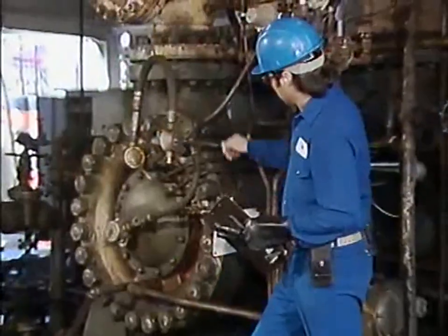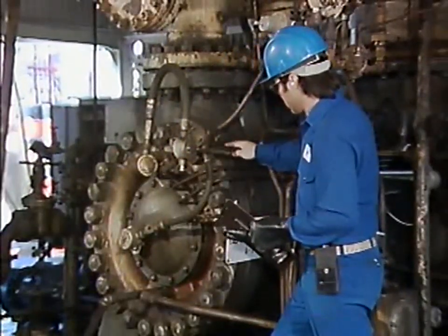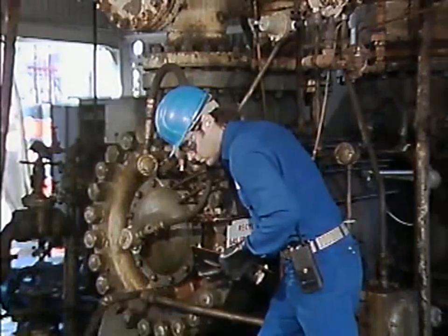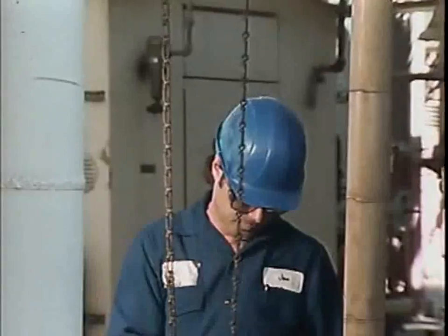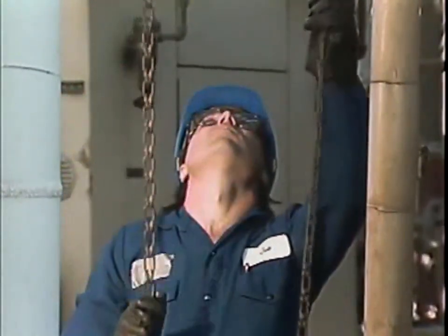Eventually, the compressor will be brought up to its minimum operating speed, which is the lowest speed the compressor can be operated at without causing surge or other operating problems. When the compressor reaches its minimum operating speed, the gas flow to the compressor can be started. Once the gas flow is started, the compressor can be brought up to operating speed at a rate prescribed by the compressor's operating procedures. Once a compressor has been started and is operating properly, it should be checked routinely to make sure that it continues to work as it should.